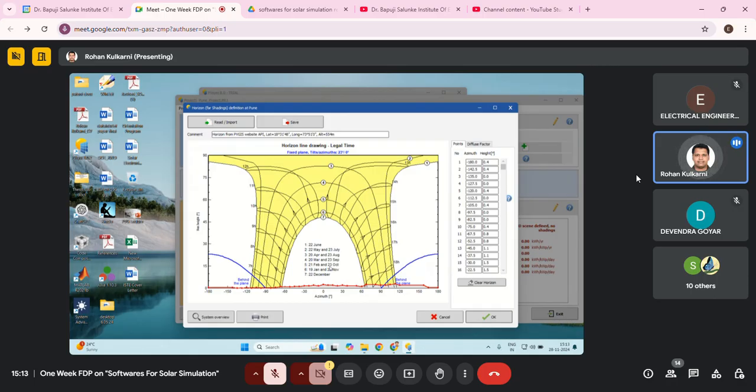If the solar panel has bypass diodes after every cell, then it can bypass that particular cell and still produce the output. In the solar panels we are dealing with, all the cells are connected in series. If you shut down one cell in the series, it affects the entire series. So nowadays people have come up with the solution of a bypass diode. Even if a cell goes down, they provide a bypass diode over there. So shadowing is taken very seriously because of the dark spot.